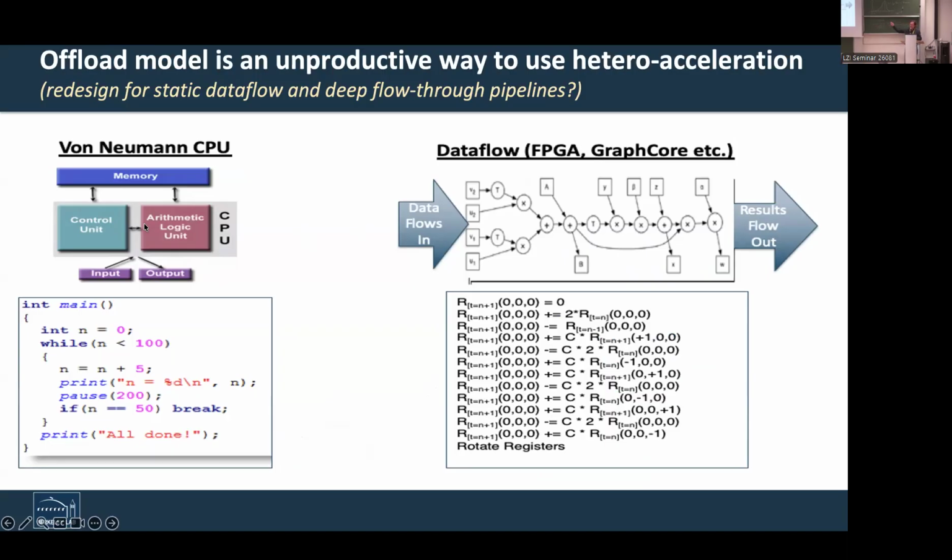Stuff goes in, out, back in, back out. When you do data flow, which is what we need for circuit design, you're just stamping out the ALUs onto the chip and the data flows through, and you're implicitly kind of trying to minimize the distance between the ALUs. And you get a lot of reuse from the pipeline dimension, which is something we don't typically exploit with MPI. And on the left too, the languages that we use to express computation are inherently oriented towards an instruction processor, where even if it's parallel, I'm doing this, followed by this, followed by this on each processor in the system.